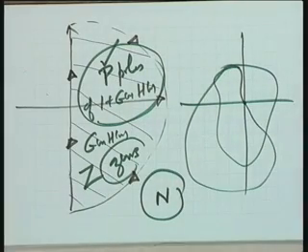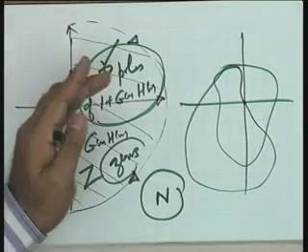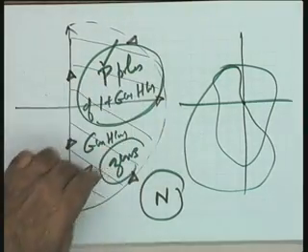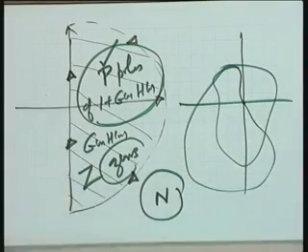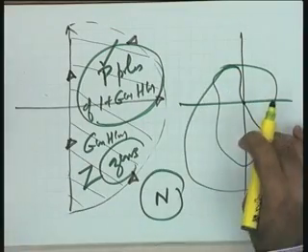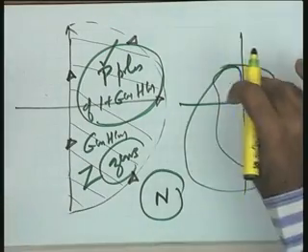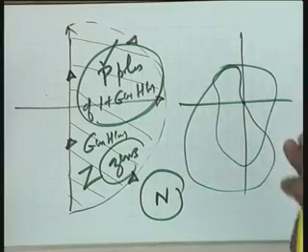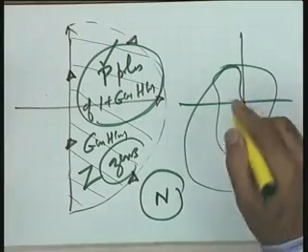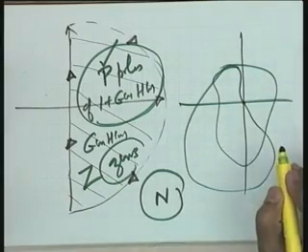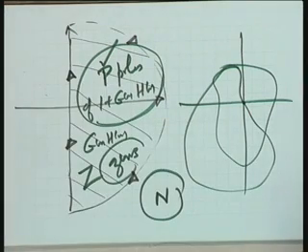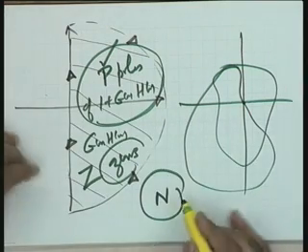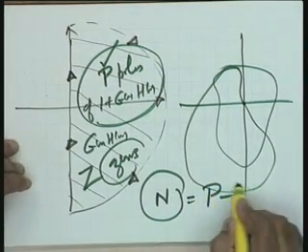Can you give me the equation, please? I want the equation from you. There are P poles of 1 plus GSHS in the right half plane and Z zeros, and there are N encirclements of the origin by the 1 plus GSHS contour. Can you give me an equation between N, P and Z? P minus Z, that is fine.